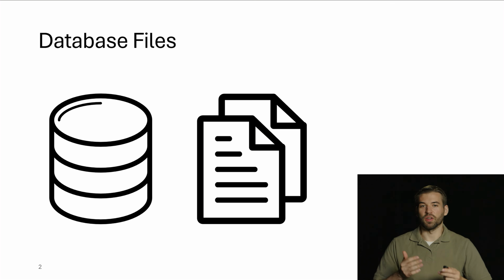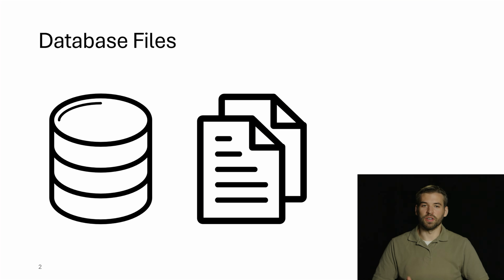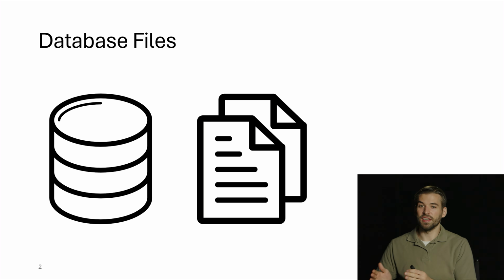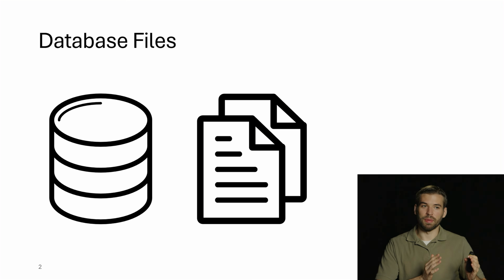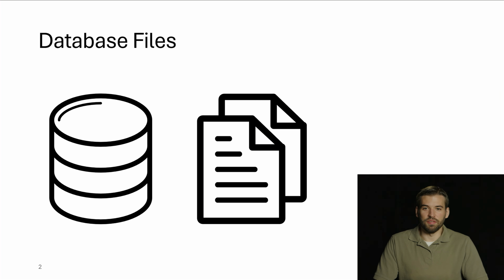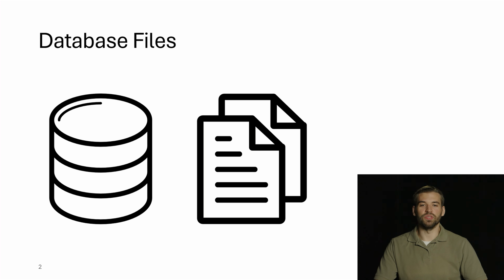For those who have taken a course in databases, you likely already know that there are different ways to format a database, particularly when storing the database on disk versus storing the database in main memory. Fortunately for us, there are a few broadly used file format standards for storing circuit information on disk. The most important ones for our purposes are Liberty, LEF, and DEF. These standards not only are compatible with OpenDB, but they're also compatible with many proprietary tools as well.